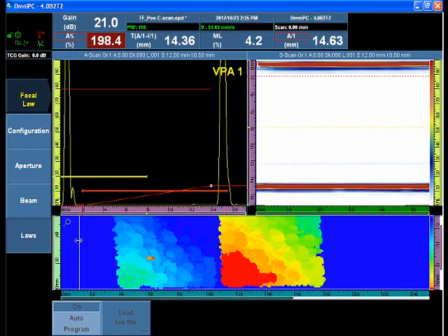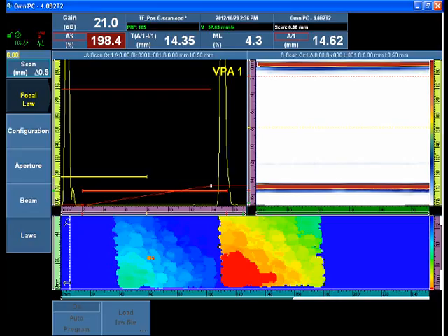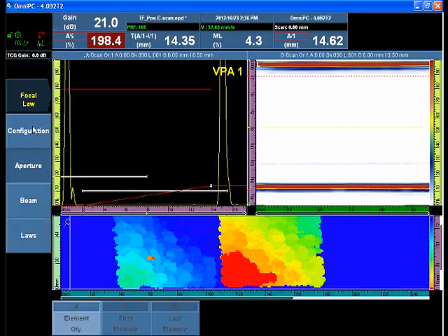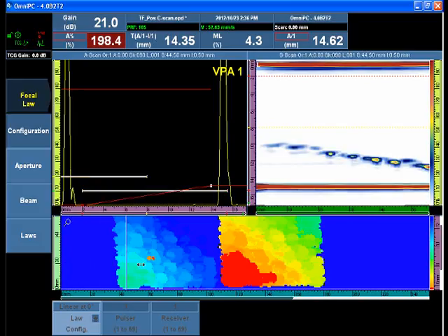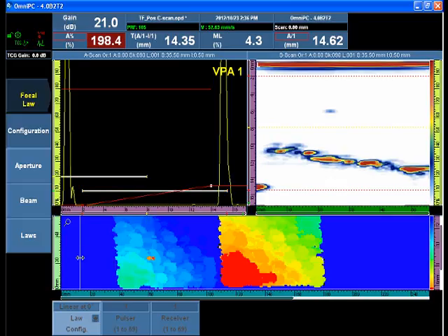So this axis on the position C scan is in actual millimeters. Again, that's another distinction between the typical sector scan type, where we get focal laws on the vertical axis. The 0 degree linear allows a real volume C scan that allows millimeters on the vertical axis, and the horizontal axis represents the probe or scanner movement through the component.